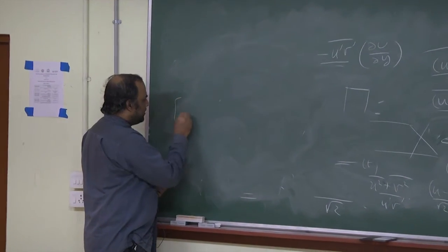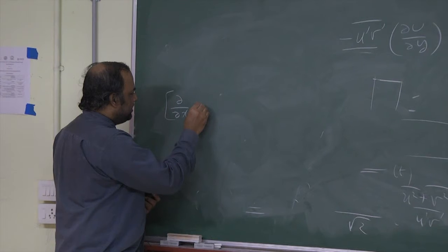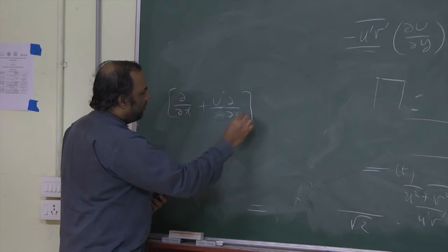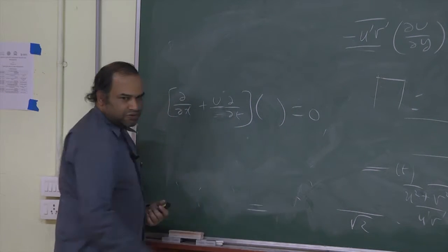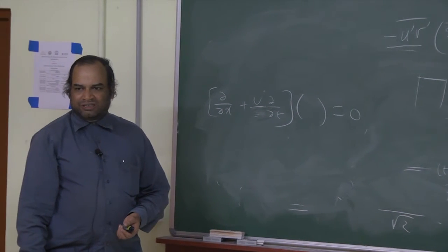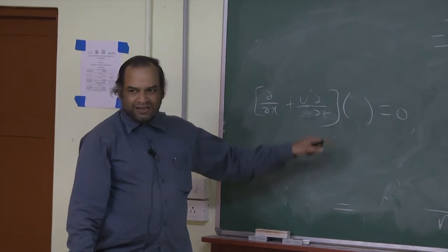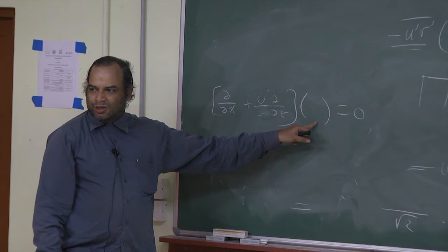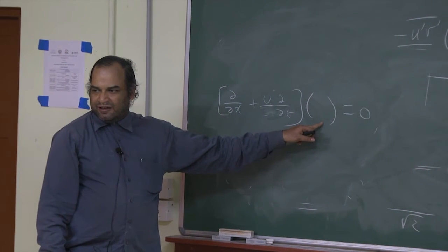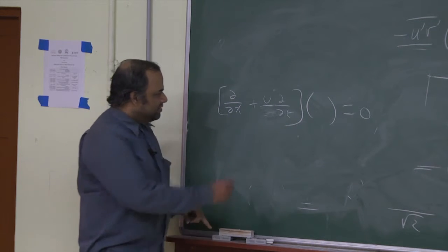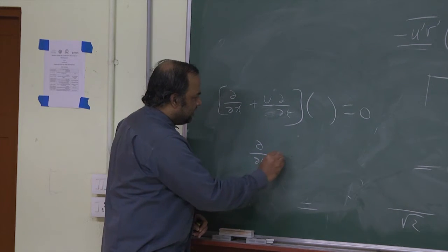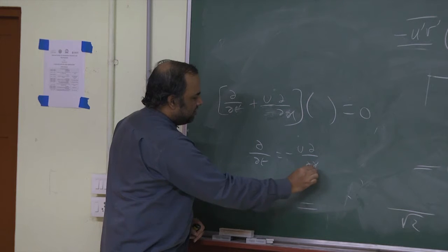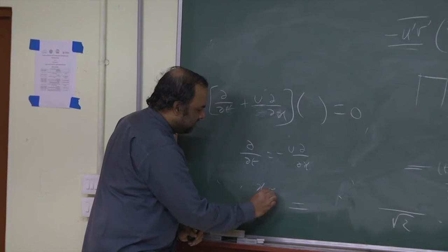So, if you now look at the advection operator, you can write it as d/dt plus u d/dx, operating on any average quantity. This is essentially the assumption. What does it mean? The advection operator, as you go along a streamline, for instance, is such that this quantity does not change by and large, it's frozen. Now for this to be frozen, when can I expect that? This operator should be like this, d/dt equals minus u d/dx, or it's like x equals ut.